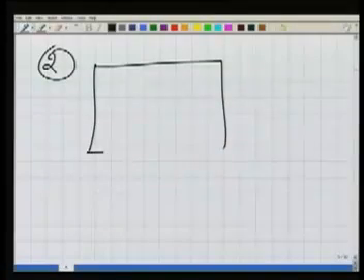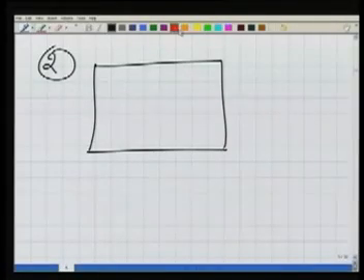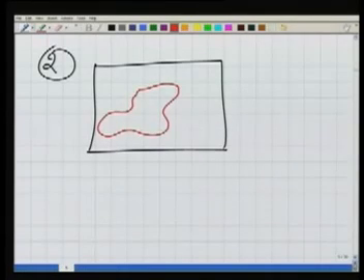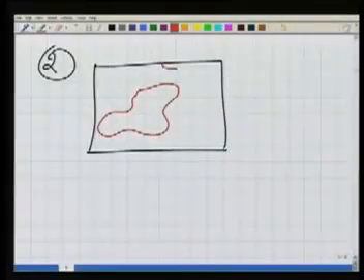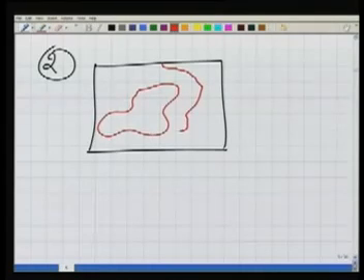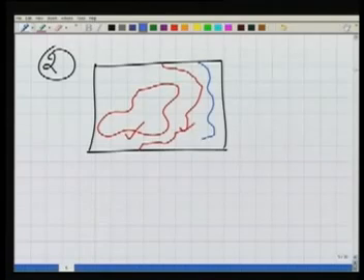Now the second characteristic, whether the contours, how do they look like on the map sheet? This is about that the contours should either close in themselves within the map sheet, or they should start from the boundary and they should close at a boundary. So these two contours are correct, but we can't have a contour which will start from boundary and it's not going anywhere.